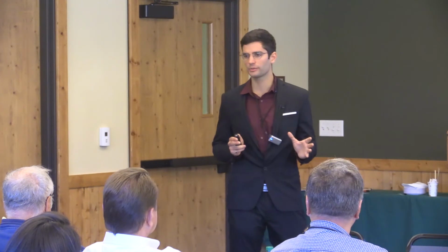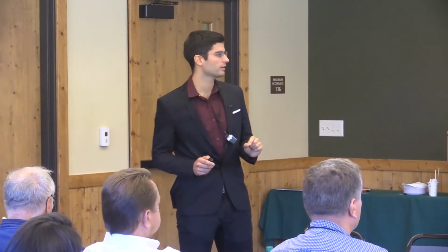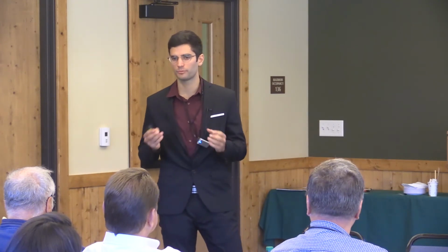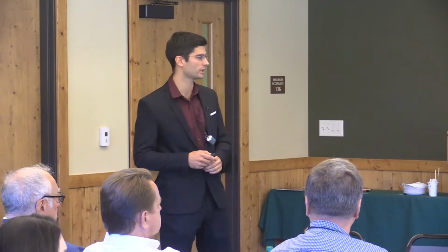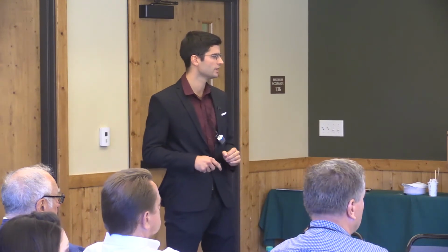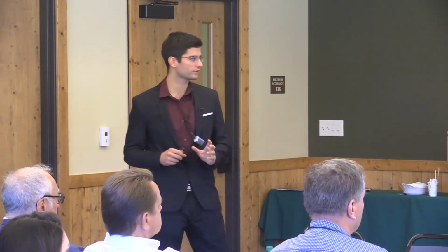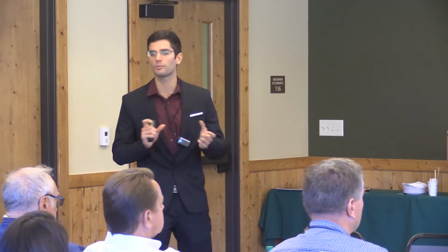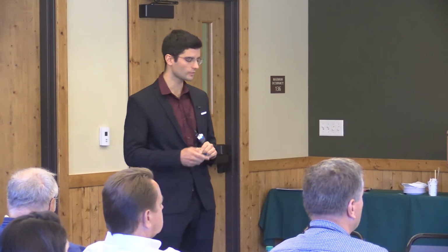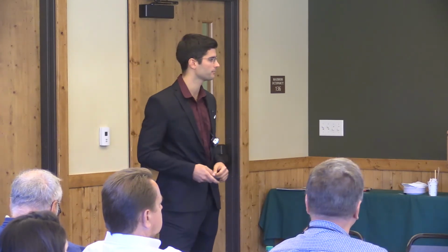It is in all materials, but it is a much lower amplitude of displacement than the piezo effect that we see in PZT4, a hard piezoelectric material. Because this electrostrictive constant, which is given in the literature, could be 8 orders of magnitude smaller than the piezoelectric constant, the piezoelectric coupling constant, which gives the displacement in relation to the voltage that is applied.